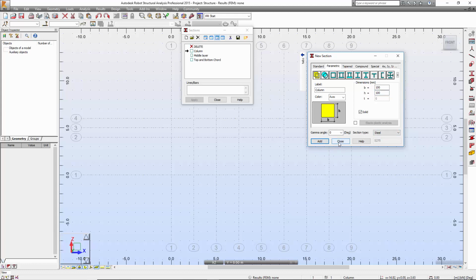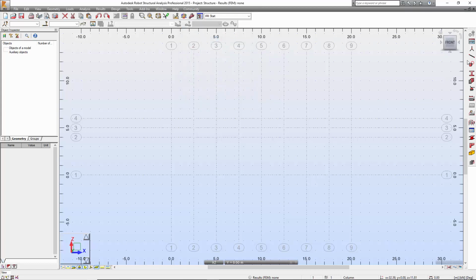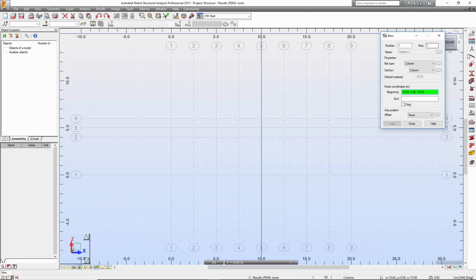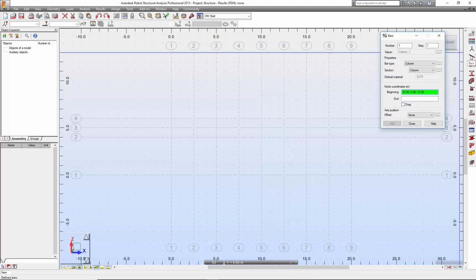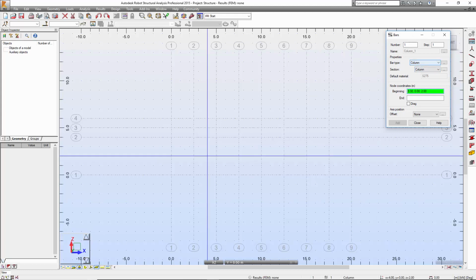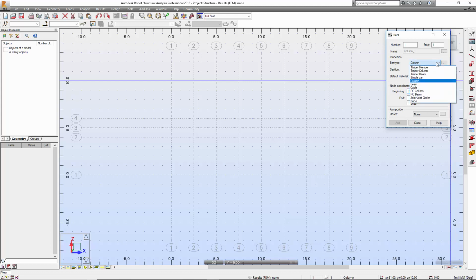So we're done. So after that we click on close, and then we're done, then this is saved in the database already, so we can close these windows as well. And then we can start to draw this structure by activating the bar mode, joint mode. So when you click on this icon and then bring up this window, what we're going to do, so let's do this one, chords top and bottom first, and then we need to make sure we use the simple bar.